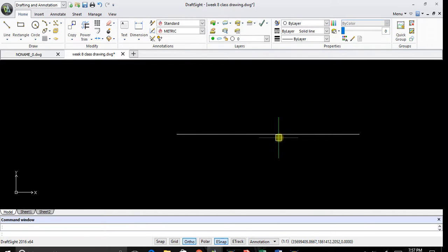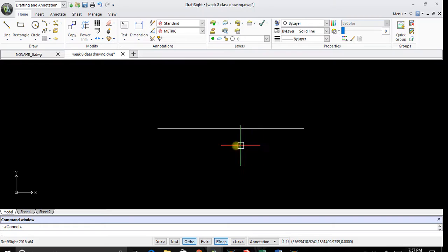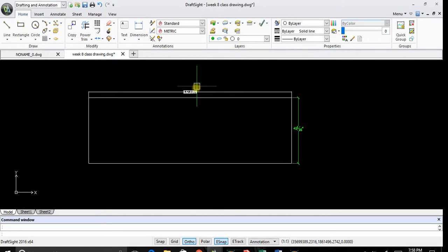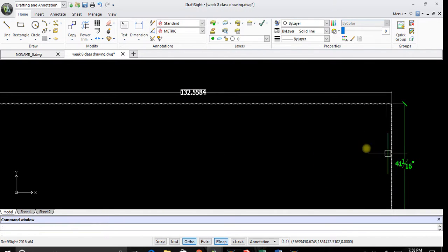As far as draft size is concerned, this line is 25 units long. But you're preparing a drawing for use for a manufacturer or a blueprint. You already need to know beforehand, is this going to be in inches or metric? There's a big difference there. So we've created two different dimension styles.